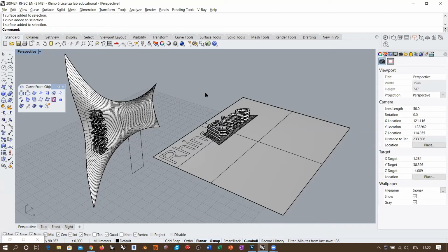Okay, I almost never recommend working with these objects here because they are quick in order to produce some kind of complex deformation, but they change the topology and the complexity of the objects in a very fast and uncontrolled way. So if you can substitute any of these commands with something as effective as the flow, for example, but producing a simpler topology, then you should consider using other methods.